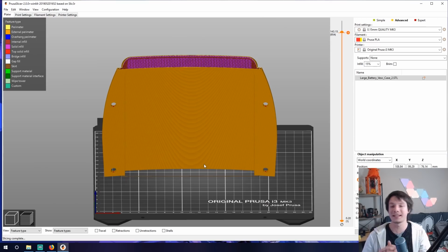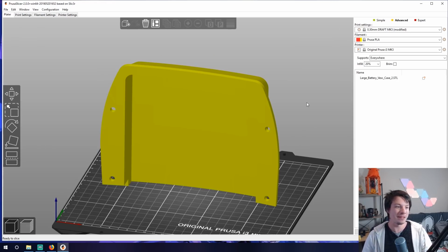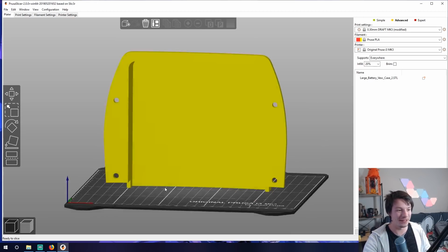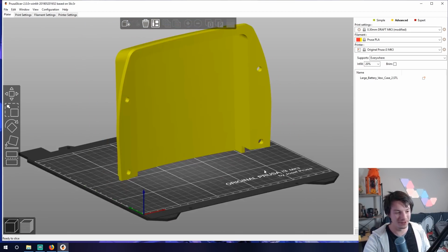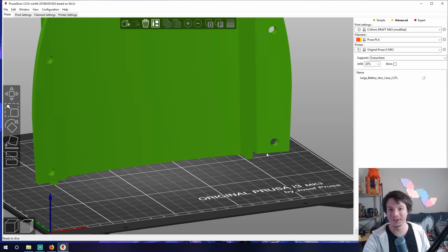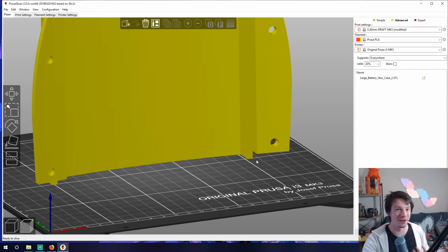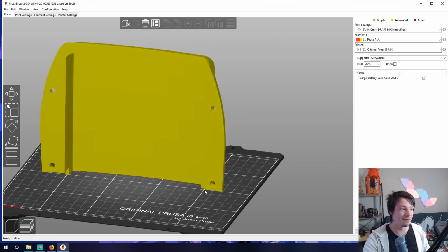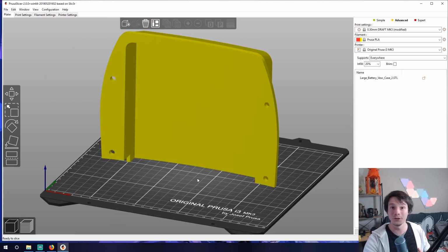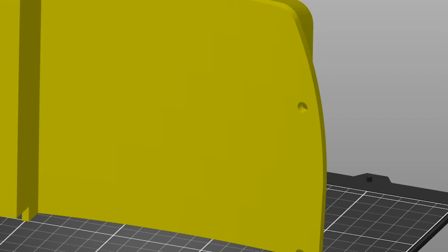So what we're going to do is take advantage of a new setting in the PrusaSlicer, which is support blockers and enforcers. Okay, so we've determined that we don't want or need support material through the entire print here. We just want it in these little overhang bits there because they really do need it, otherwise the print's going to fail. And we can do that in PrusaSlicer using support enforcers. It's very easy to put them in now. So let me just show you.